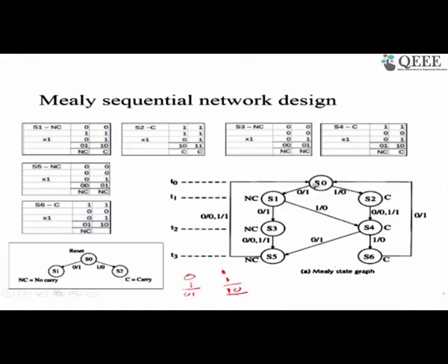So we will do the following. So this is the initial state graph which we will put here. So for S0 we go to S1 or S2. With these transitions, S1 represents there is no carry, so we will indicate it by NC. S2 represents there is a carry, which we will indicate by C. Now we will look at S1 and then see what happens when the next bit arrives. When the next bit arrives, again we have to add a 1 to that position for an XS3 conversion, and there can be a carry or no carry. Incidentally, in S1 there is no carry.